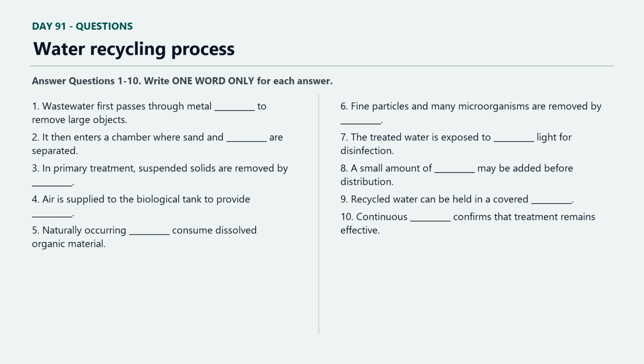It enters a large settling basin where movement becomes slow and relatively calm. Suspended solids that are denser than water sink through sedimentation and form a layer of sludge on the bottom. Oils and grease may rise to the surface and are removed by a separate skimming mechanism. Rotating scrapers move settled sludge toward a collection point without disturbing the entire basin. Primary treatment removes a substantial part of the suspended material, but much dissolved organic matter remains. This dissolved material requires biological treatment.